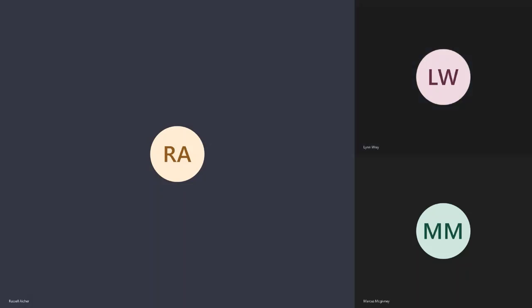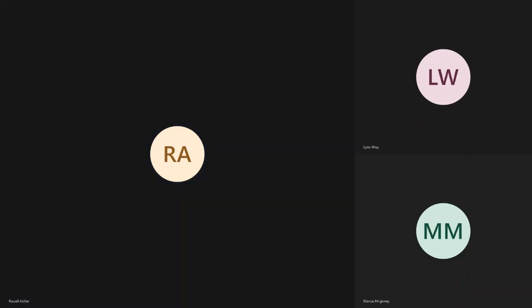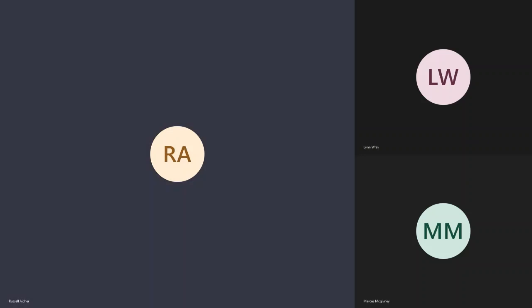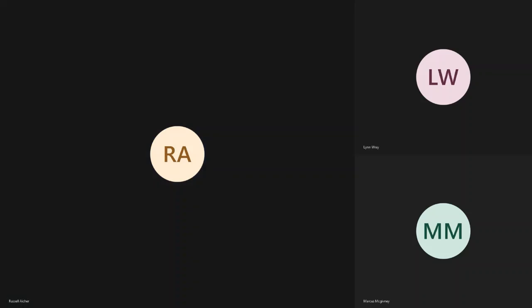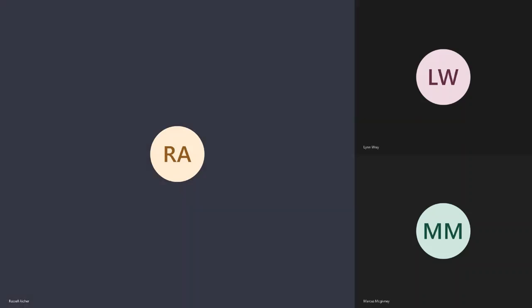The cluster tolerance basically tells it, everywhere there's an intersection, search this distance, whatever your cluster tolerance is, and if there are extraneous points or lines in that distance, snap them all together to minimize the number of slivers. You can trash your data this way if you set your cluster tolerance too high. Whatever you set it to needs to be in the same units as the coordinate system. So if you're in geographic, you have to figure out what your cluster tolerance is in degrees.